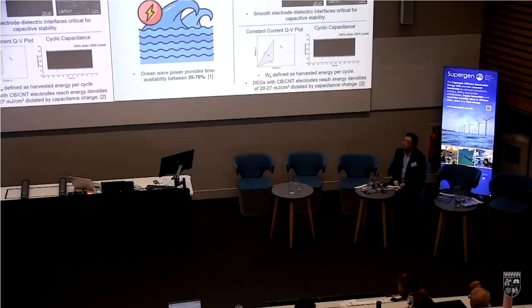Our research is focused on developing the compliant electrode materials and dielectric elastomer generators. The microstructure that you see shows clean, low-defect interlayer bonding, which supports and improves the reliability of cyclic capacitance behaviors in these materials. Similar research has shown really high energy densities, which is one of the bottlenecks in viability. Thank you.